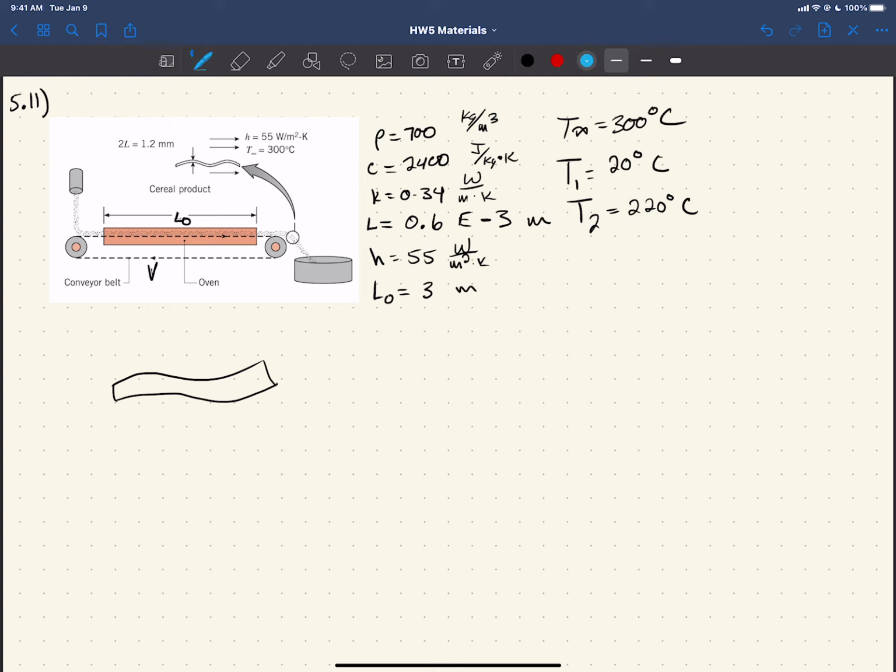And so if you didn't know that we were in the lumped capacitance section, and you didn't know we were solving problems along the lines of doing the Biot number, checking if it's less than 0.1 and all that business, I would start with an energy balance. And so first off, you know that there's E dot out by convection. We're just going to call it E dot out. We don't necessarily know if it's in or out, but we're just going to call it out, and the signs will work themselves out.